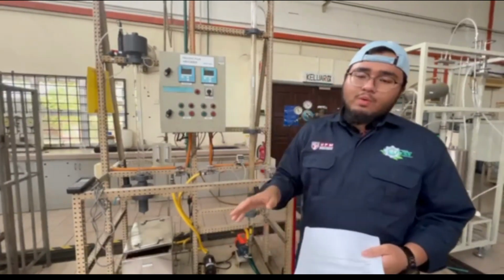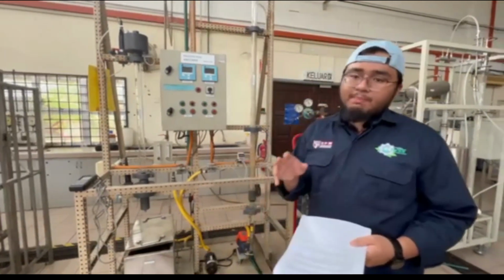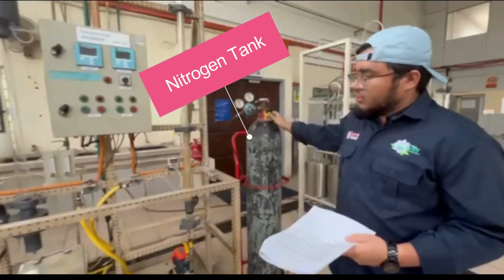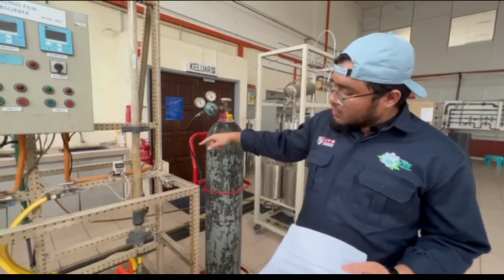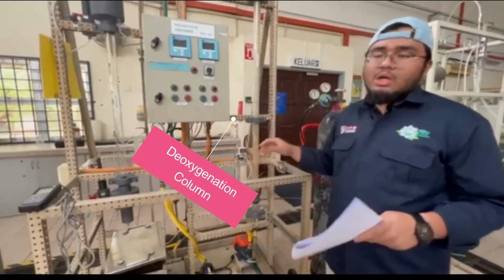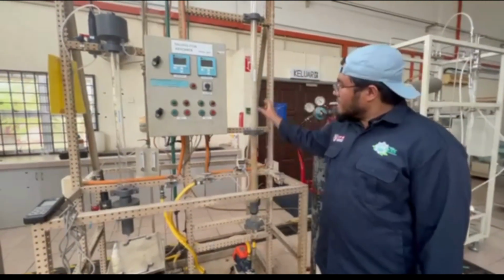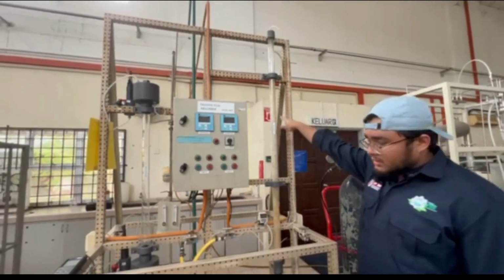Before we show you how we conduct this experiment, I would like to show you some of the important parts of this absorber system. We start with the nitrogen tank, which is our nitrogen source. The nitrogen will be supplied to the deoxygenator from the bottom, because we want to deoxygenate the water using nitrogen. We supply the nitrogen from the bottom and the water from the top, so the water comes down and the nitrogen goes up.